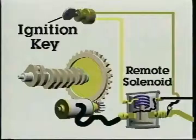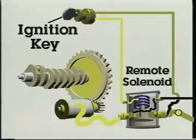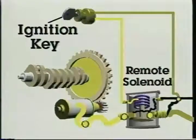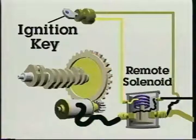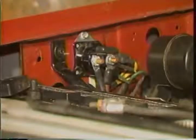This animation shows the basic purpose of a starter solenoid. When the key is turned to start, a small current flows through the solenoid windings and ignition switch. This pulls up on the plunger and closes the solenoid contacts. Hundreds of amps can then flow through the solenoid to the starting motor.